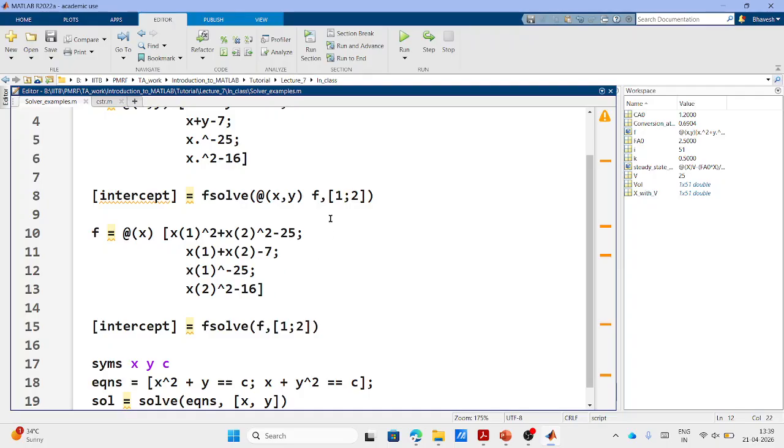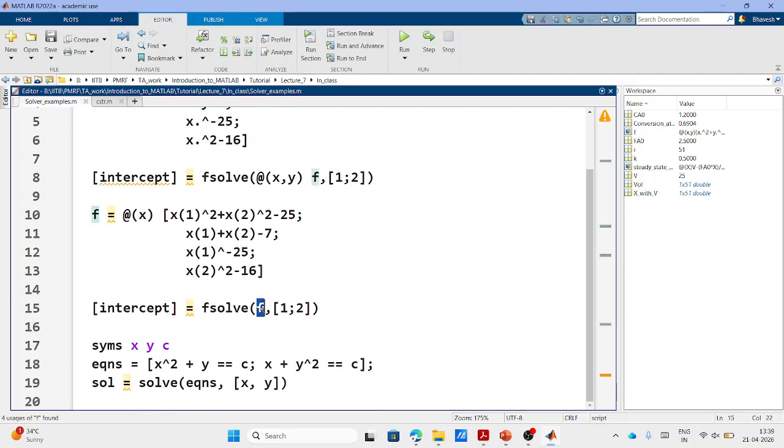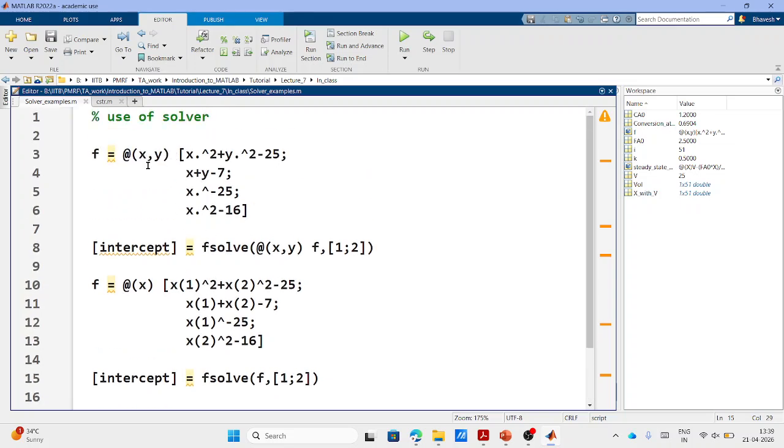Because here what we have to provide is the fsolve function value and the initial guess value. Now, if I have a multivariable function, let's say x, y, and z also, then I would have to provide a value for each. And fsolve is not designed in that manner where you can provide x, y, z as multivariable data. So whatever variables you have, you have to provide them in one vector format only, or let's say matrix format, anything, okay? So you have to provide it in one go. That's why this portion was not working.